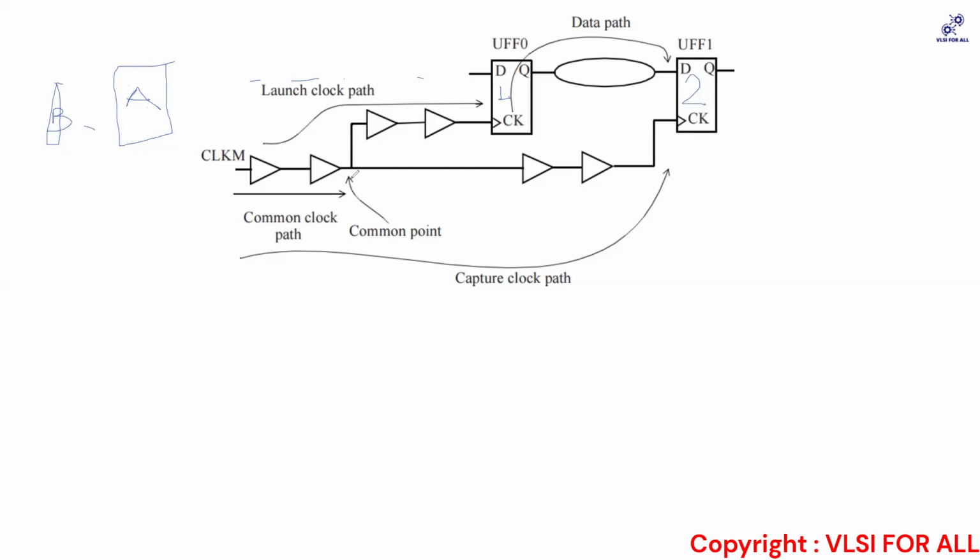So if someone asks what a launch flip-flop is in the design, you say that when you are considering a particular timing path, during that analysis, the flop which launches or sends out the data is the launch flip-flop, and the flop which receives or captures the data is called the capture flip-flop.